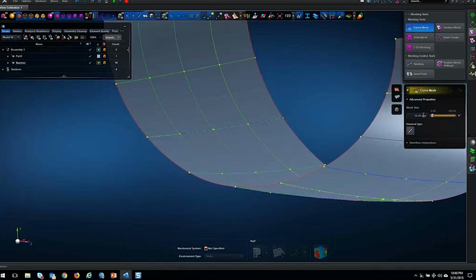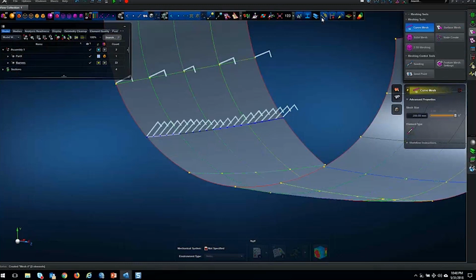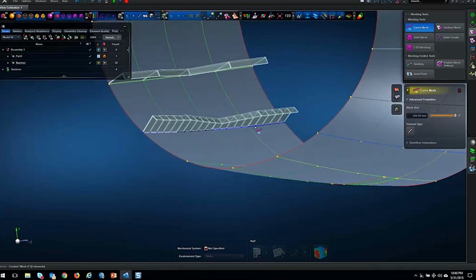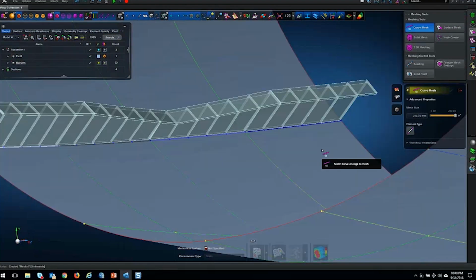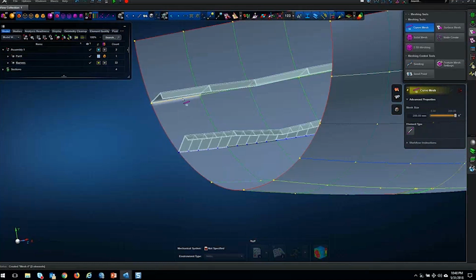Let's say I would like to create the curve mesh with 200 millimeter span for those curves that I assigned the rendered shape. So these are the beam elements that I created, and if I assign that one, now you can see those are the beam elements that I created with respect to those curves, right? And I could do the same thing here too.